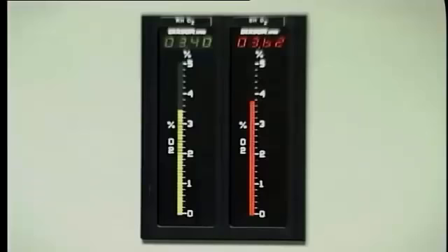So it is apparent that one way to monitor the effectiveness of combustion is to analyze the content of flue gas. However, in practice, it is difficult to accurately measure these proportions due to the fact that the water vapor may condense in the measuring instruments. The preferred method is to measure the proportion of excess oxygen which exists in the flue gas.